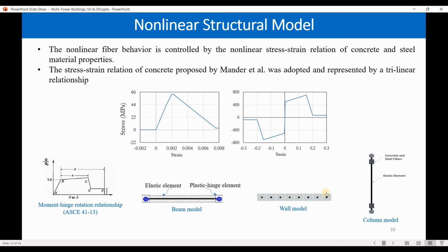Also, we can assess the axial force bending interaction, the influencing factors such as the capacity to resist both tension and compression, and lastly, the redistribution of stress along the cross-section. Therefore, if this member fails, we expect the program to redistribute the force inside the system. Therefore, we are expecting to have degradation in stiffness due to cracking. This is actually the idea.